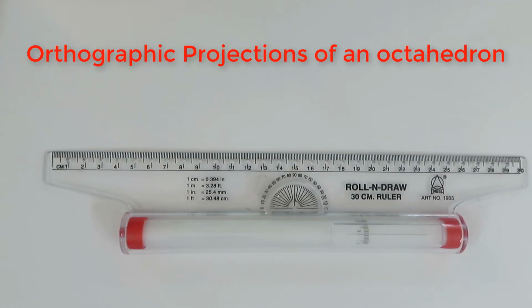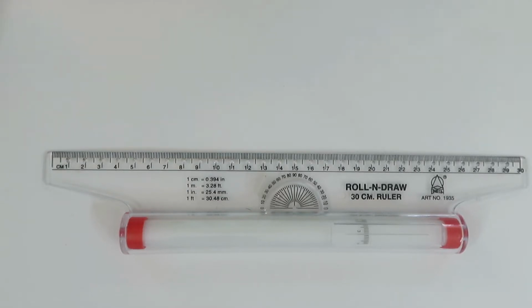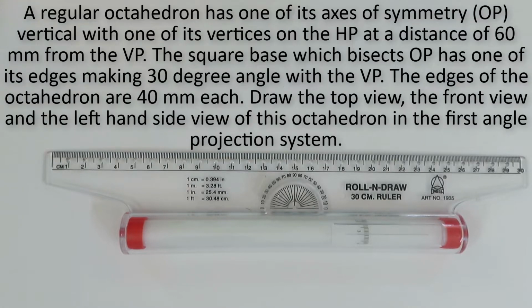Hello, today I would like to solve the problem of orthographic projection for octahedron. So the problem is: a regular octahedron has one of its axes of symmetry vertical with one of its vertices on the HP at a distance of 60 mm from the VP. The square base which bisects the axis has one of its edges making a 30-degree angle with the VP. The edges of the octahedron are 40 mm in length.